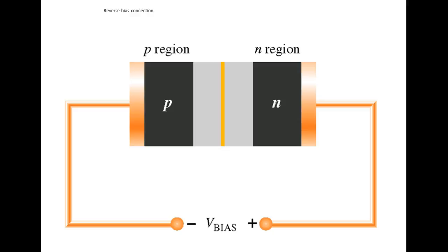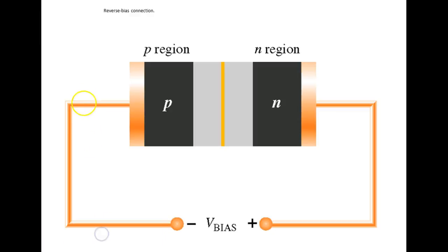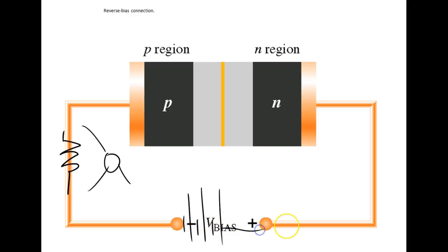So if I came over here, and we don't need a resistor, by the way, but if we had the original circuit that we had, and then we would have a resistor over here. And then I would come over here. What would we measure across the resistor? If this right here was 10 volts. Yeah, I would measure just about 0 volts. In fact, that's what we measure. Why don't we measure voltage?